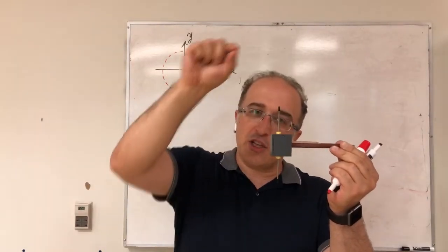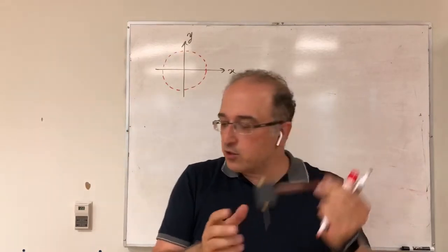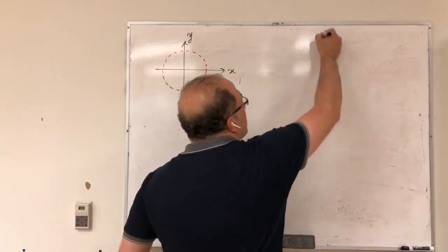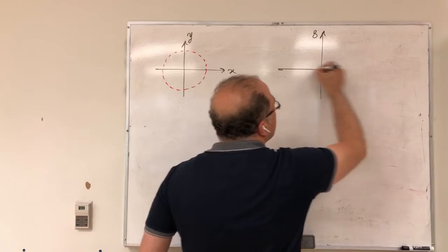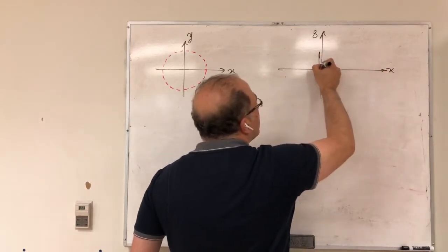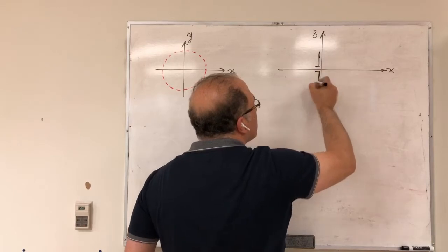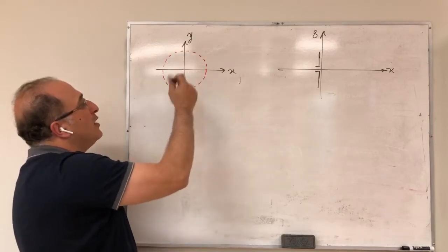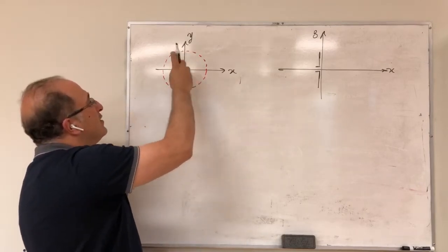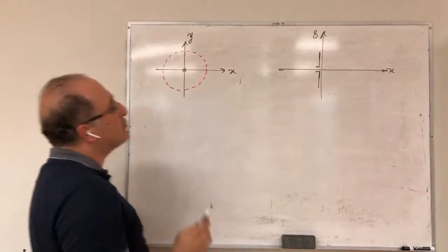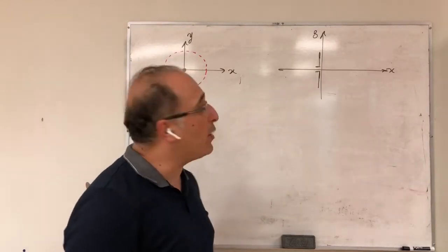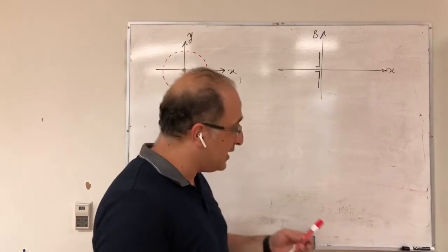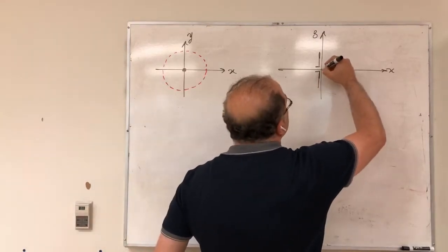So I want to change the point on this plane like that. So that would be another cut of the antenna. So if I plot, this is my Z axis and this is my X axis. And remember, this was my antenna. Antenna is along Z. I cannot plot the antenna here because antenna is like this, is in the Z direction. So if I make a cut, the antenna looks like a point. This is in fact your antenna along the Z axis. But here, because I have Z axis, I can plot my antenna. And for this specific type of antenna that I showed you, the pattern here would be something like this.